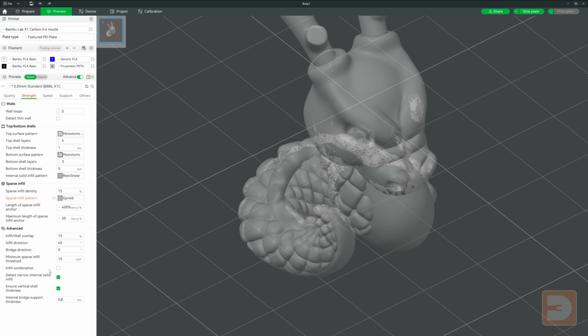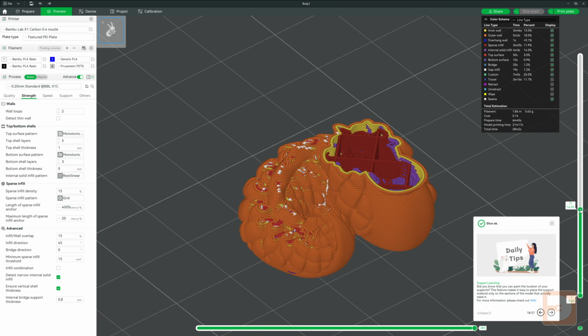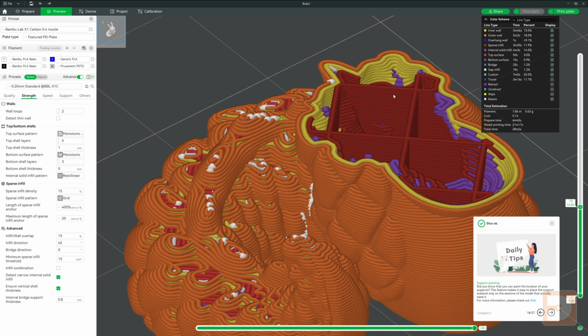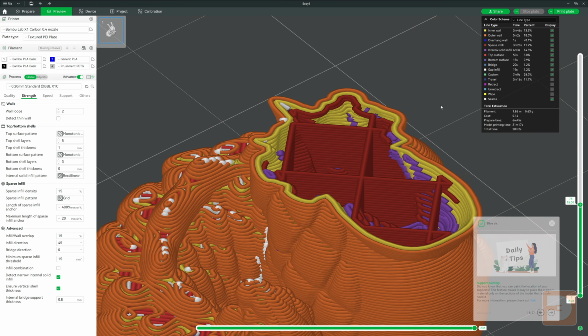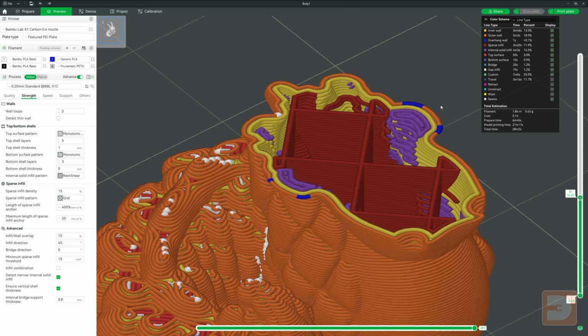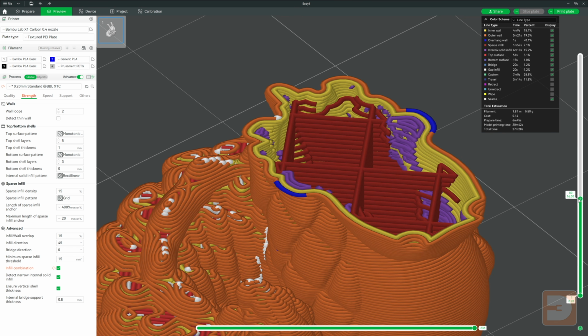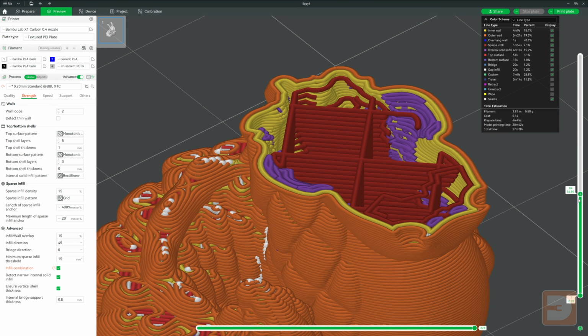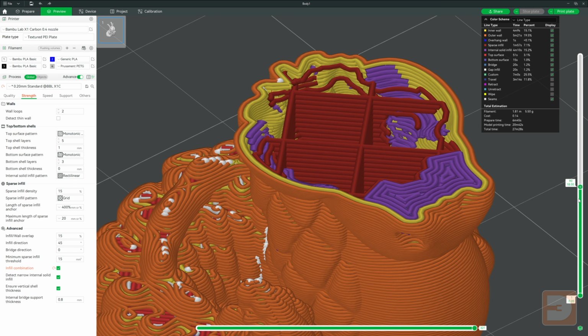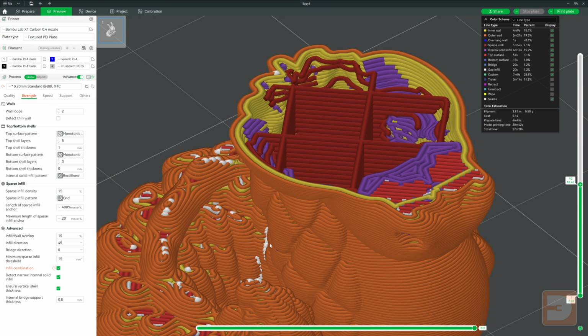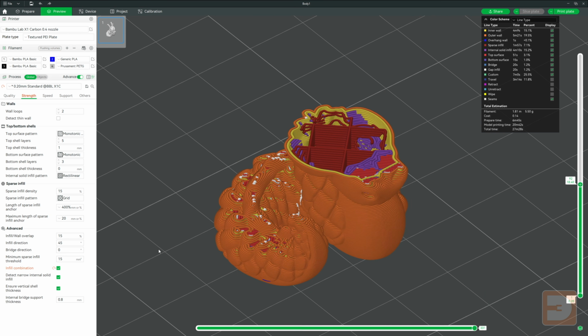Infill combination is a time-saving mechanic. It basically combines several layers of infill and prints them together as deeper extrusion lines, whilst printing your exterior perimeters at the layer height you've set. So let's say you had your layer height set to 0.2mm, normally your infill would also be printed in 0.2mm layers with the rest of your print. With this activated, however, whilst the walls are still printed at 0.2mm, the infill is only printed every 2 exterior layers, meaning that the infill is being printed at roughly 0.4mm layer height.